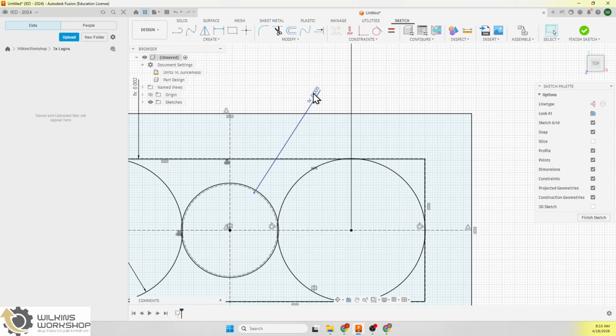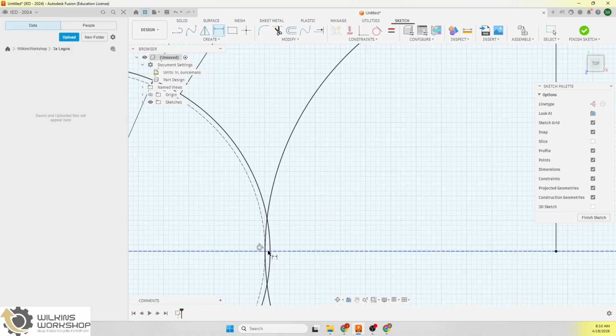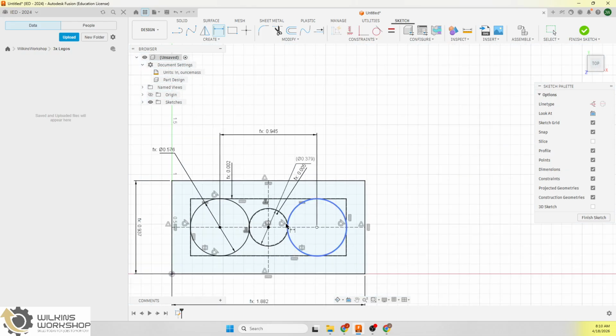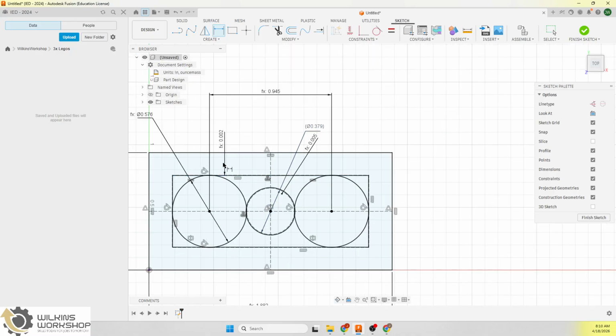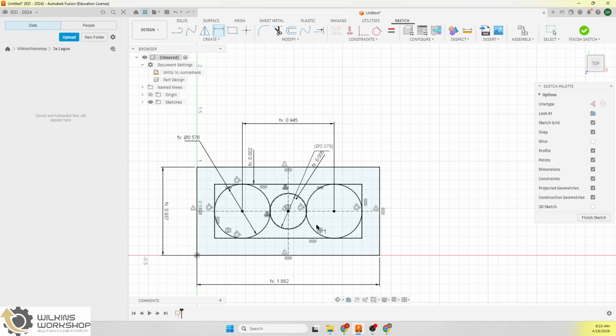I like to put this up here, so if you're going to look for how did I find that dimension, you can double click on it. And then I also am going to just show what this dimension is so you can check it. So it should be 0.379, and it's a driven dimension because we've already dimensioned it to this. So it's saying, hey, this is going to change based on this. But that squeezes a little bit tighter in the middle when you have these parts, and that's what we found works really well. This is really all the dimensions you need now for your part.